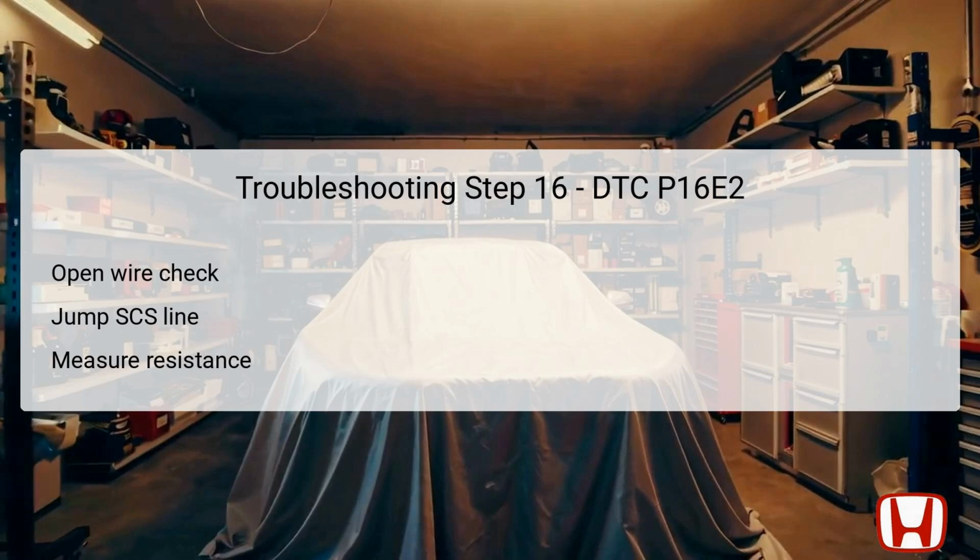After this, the alternator and DC-DC converter connectors are disconnected to conduct resistance measurements across available test points, allowing for full details on circuit integrity. Achieving a measurement of 1.0 ohm or less signifies intact wiring. The alternative results will initiate a comprehensive analysis leading to repairs made to an open line noted within the LIN pathways monitored.